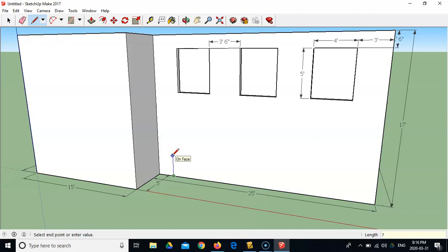We're going to make this 7 feet high. And we're going to put a couple side lights on it. So the side lights, or the side windows, are going to be 1.5 feet, so 1 foot 6 inches. And bring that back down until it clicks on that bottom line. Go back to the top. We're going to make it a 3-foot door. Then go back to the bottom, back to the top, and do the 1 foot 6 again. 1 foot 6 inches. Whoops, did a funny measurement there. Let's escape here. Let's try that again. 1 foot 6 inches. There we go.